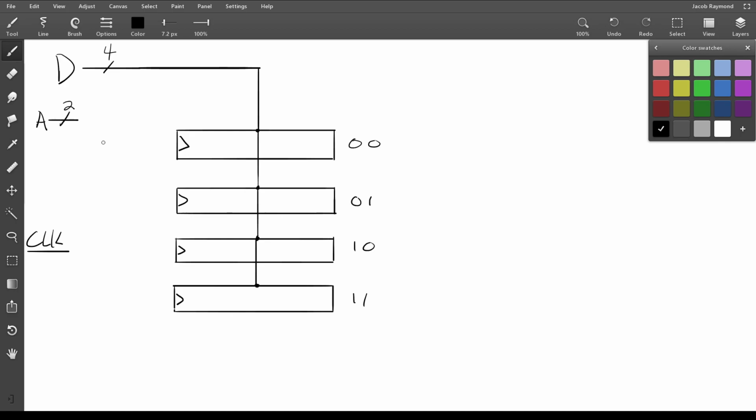Well, for those of you who have a little bit more experience with basic circuitry, this is the exact location where a demultiplexer would be ideal. However, if you're not familiar with a demultiplexer, we'll actually want to use 2 different components to effectively create a demultiplexer. So the first one is going to be a binary decoder.